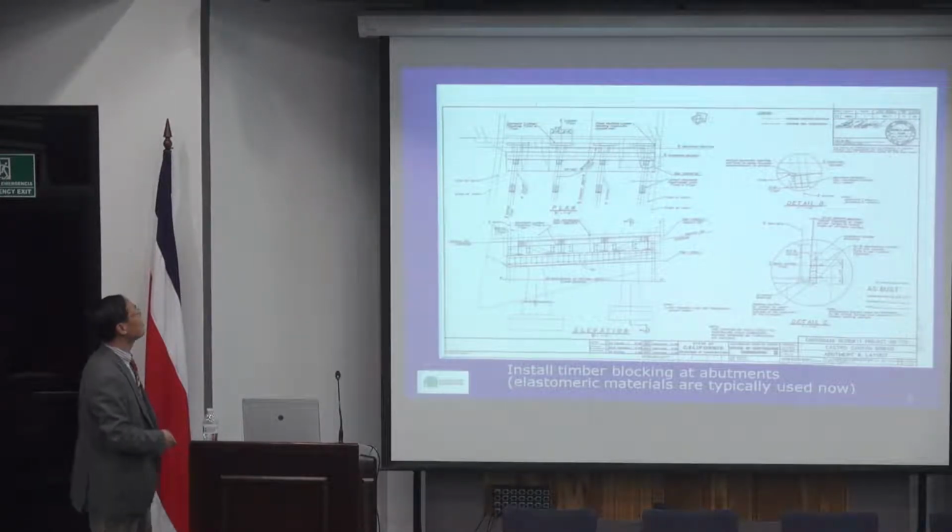And these are basically the details, and so they try to, these are over piers. Over piers is the same. We try to link a lot of structures into the pier bent to prevent them from being free to move.